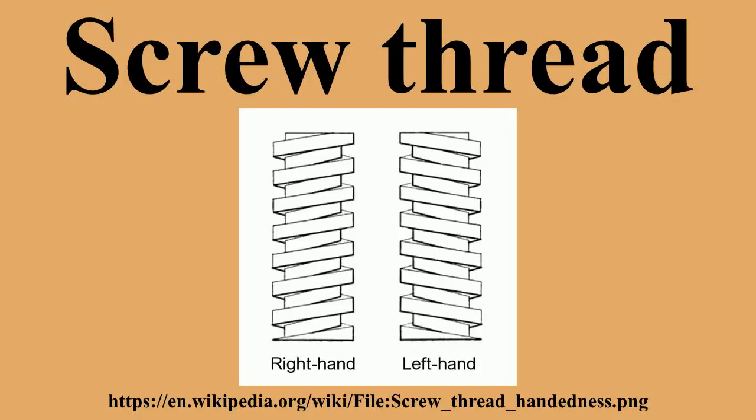The major diameter of external threads is normally smaller than the major diameter of the internal threads, if the threads are designed to fit together, but this requirement alone does not guarantee that a bolt and a nut of the same pitch would fit together. The same requirement must separately be made for the minor and pitch diameters of the threads. Besides providing for a clearance between the crest of the bolt threads and the root of the nut threads, we must also ensure that the clearances are not so excessive as to cause the fasteners to fail.